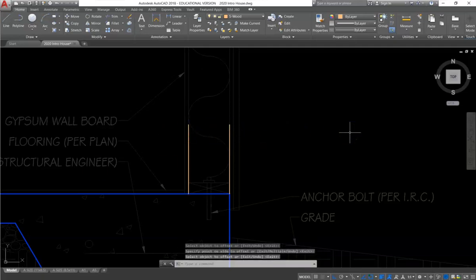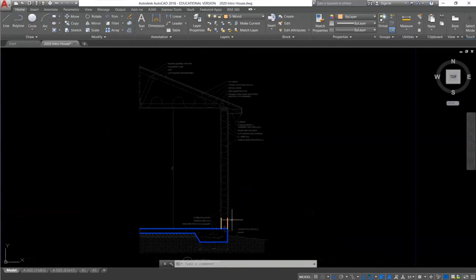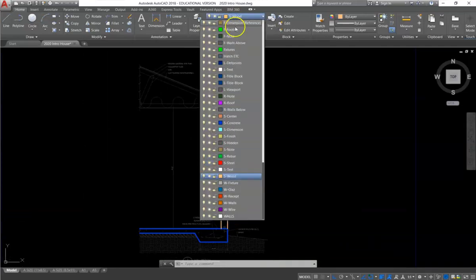And that's the thickness of the stud wall. Before we begin drawing the height of the stud wall, which you can see on my drawing, you will need to first locate your finished floor line and your finished ceiling line. So the floor line where you stand in the home, and then the ceiling line is where the ceiling would be. So we need to note the height of that.